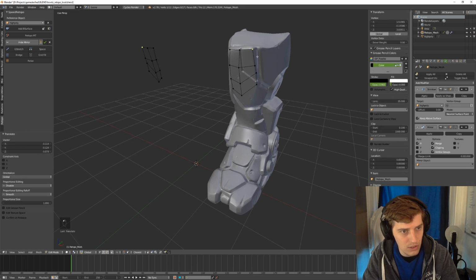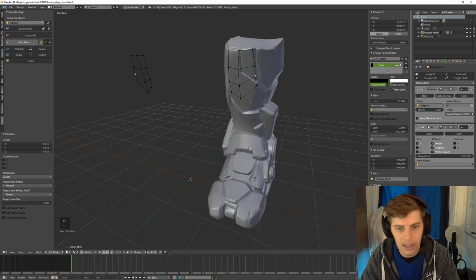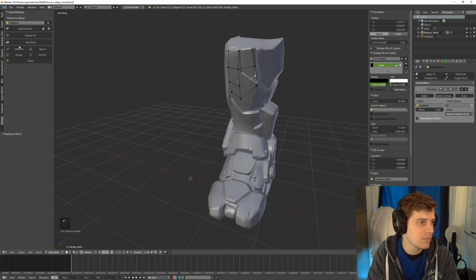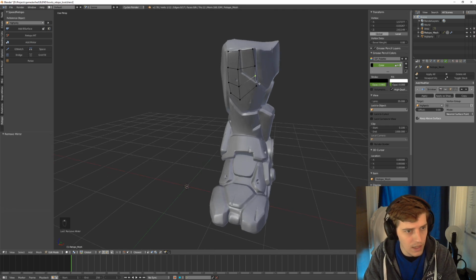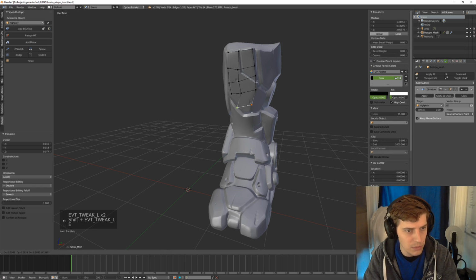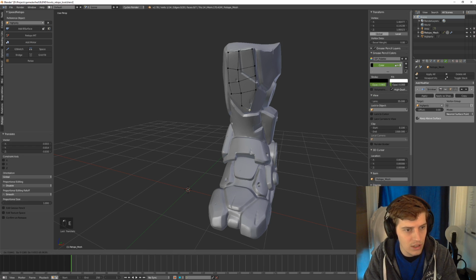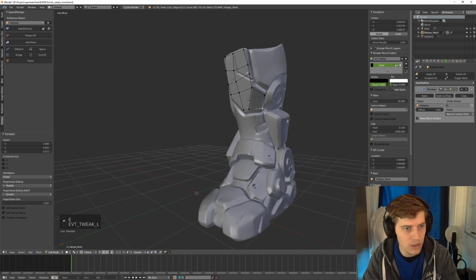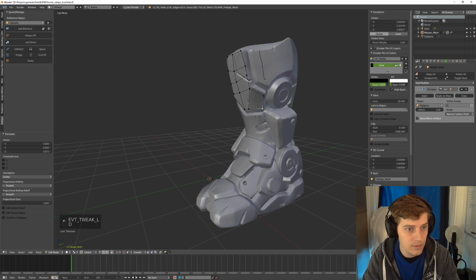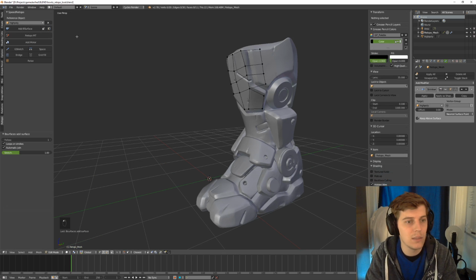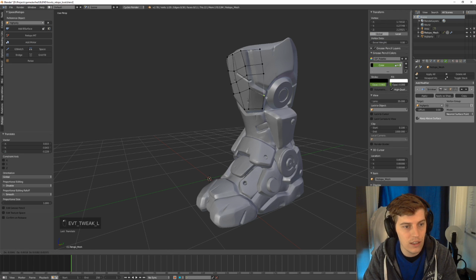And then you can start dragging. And you'll see that it's mirroring, and that's because of this mirror modifier, and you can basically just turn it off in the tool here. And now I can just continue to work like I've been working before by extruding stuff and extruding more stuff. And if I want, I can draw another line and then select these and press Add B Surface, and as you can see, it's just connecting all of these.